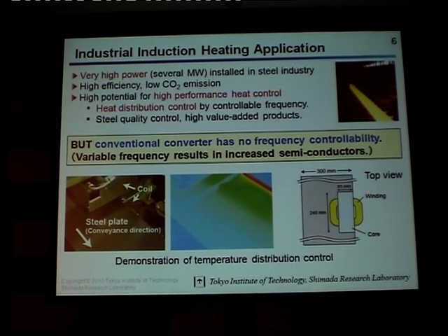It has high potential for high performance heat control. If the frequency can be changed, heat distribution control can be done. But the conventional converter has no frequency controllability, because of the very big capacity of the converters, and in induction heating the power factor is very low. So they use a series capacitor, so they cannot change the frequency. Variable frequency results in increased semiconductor rating, a very big semiconductor rating.